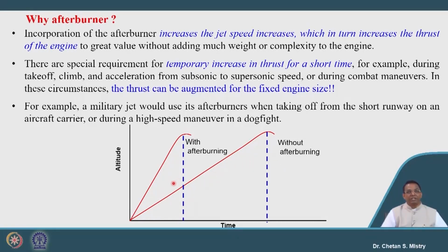So in this case, suppose for naval application where my takeoff length is short. Okay. Under that condition, within the short distance available, if we operate the afterburner, we will be able to achieve altitude in a short distance and short time. That is a major requirement. It is also helpful for high speed maneuvers in dogfight configuration. So we can say the afterburner has a special application towards military purposes.